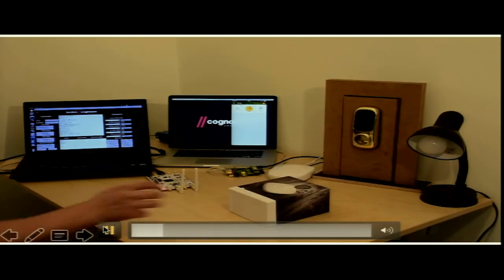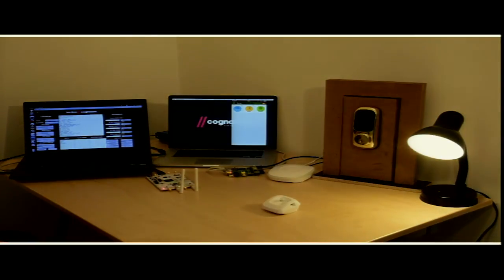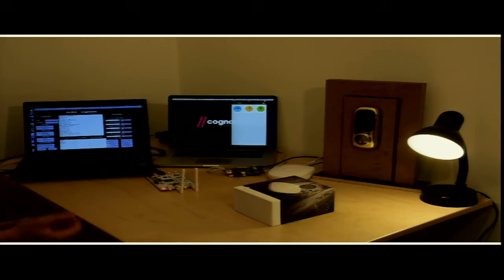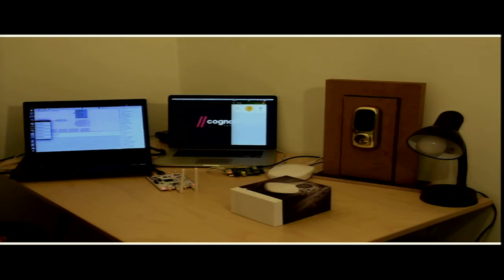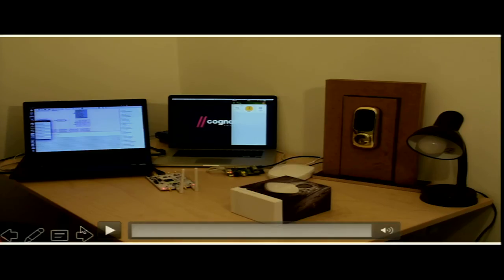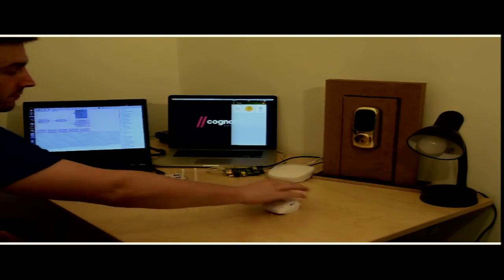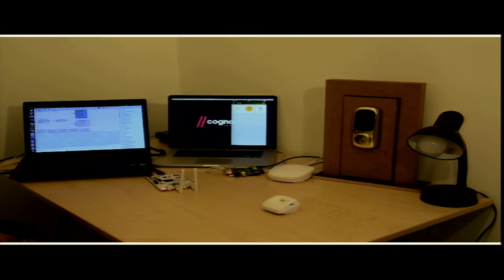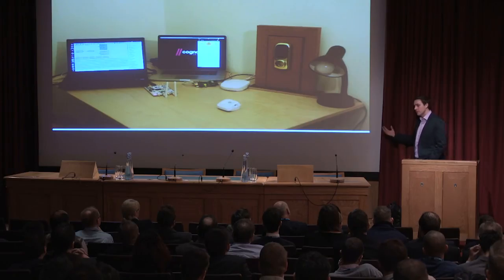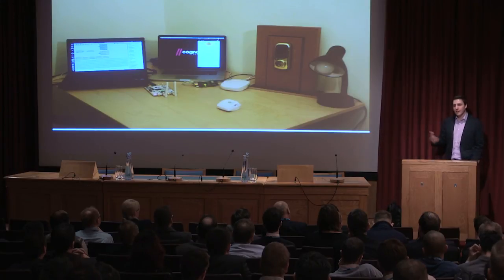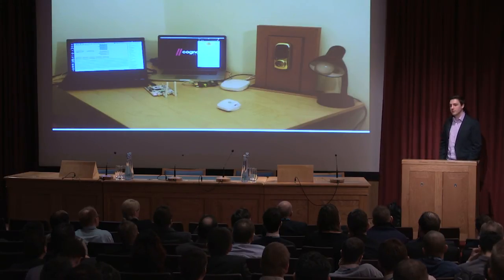You see under the box there is a motion sensor, and when I lift the box, the light goes on and a motion is detected. That's the normal way. And when you just do a simple jamming, you just kill me. So it's just the easiest jamming, and the problem is there is no jamming detection in there, and also if you jam for longer than 10 seconds, the motion sensor will not retransmit the motion. So you just jam the signal, walk into the house, and get back out of there, and nobody will ever notice that there was motion again.